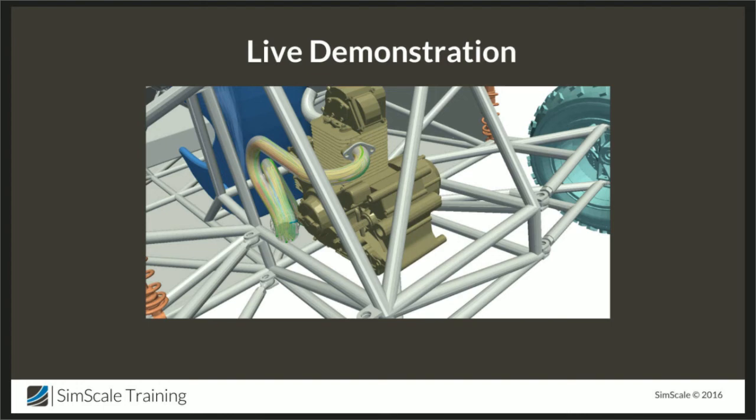The main aim in designing a system like this would be to have a very smooth process through which the flow can be directed out of the engine. For that purpose, you would have to design your engine exhaust manifold in such a way that there are no blockages or recirculation zones inside the exhaust manifold.